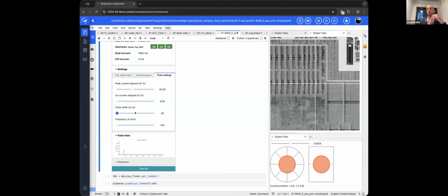Or maybe you want to target multiple cycles because your operation of interest lasts multiple cycles. Or on the contrary, you are trying to target, on a pipelined architecture with, let's say, fetch, decode, execute steps, just one of these steps within one cycle. So you can also basically change the pulse width this way.